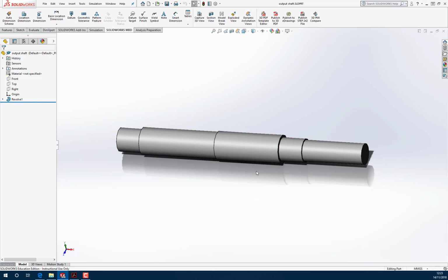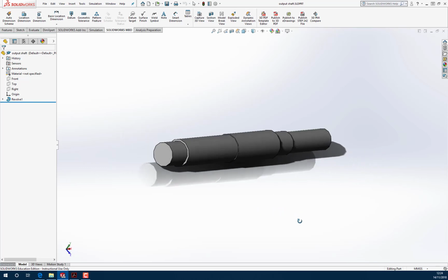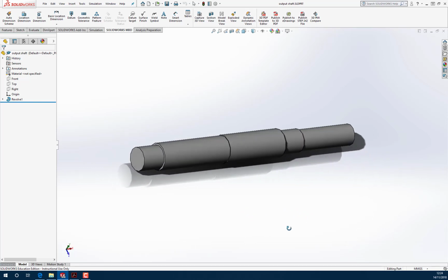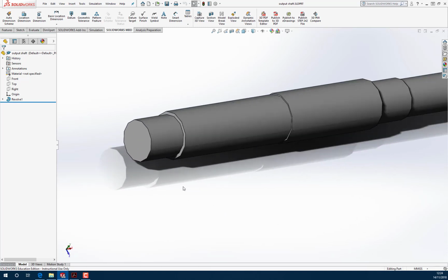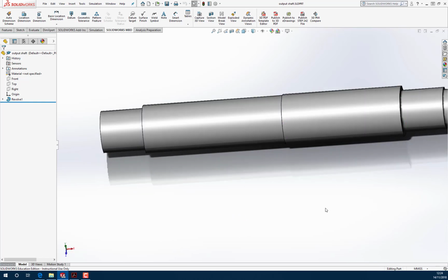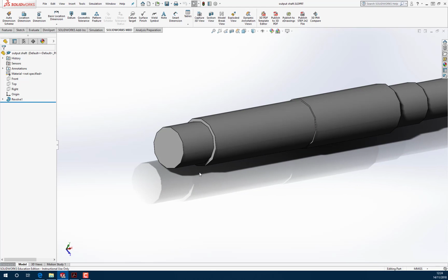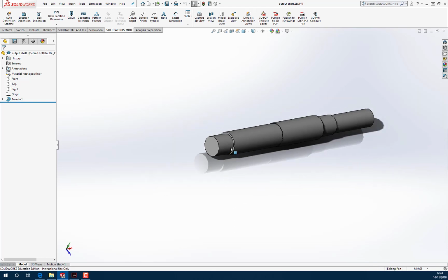Okay. And we need to control this segment of the shaft to prevent it oscillating as the shaft rotates on this axis. In addition, we need to load all of the shafts into the gearbox so that all one end are flush with each other, and that end on this particular shaft is here, so that will be butted up against the bearing, and then everything else is spaced out along the shaft from that surface. So that's going to be another datum. So we've got two datums, this one here and this one here.